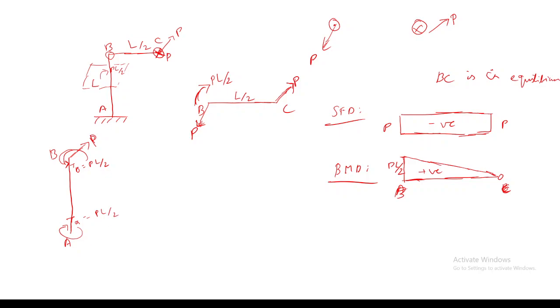And you will get a shear force also, which will be opposite to the force at point B. And then will there be any moment? Yes, sir, P into L. In which plane will this P into L bending moment act?